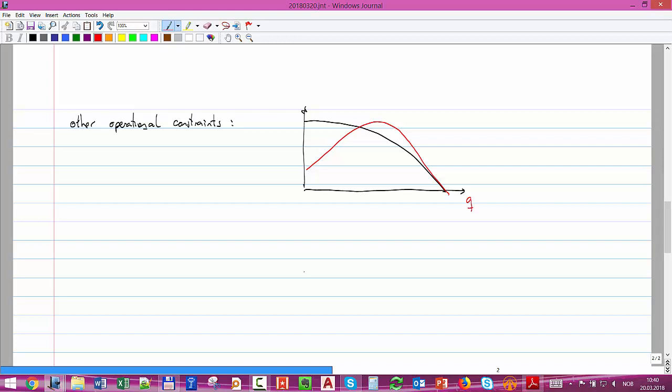Sorry, Q delta H, that's delta H, and that's the efficiency. So we usually want to operate within a range from this best efficiency point. We want to operate up to this level and up to another level. Otherwise, here the losses become too big. The temperature starts to increase too much, and it's really not very efficient, the pumping process.